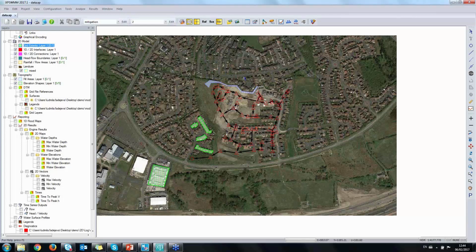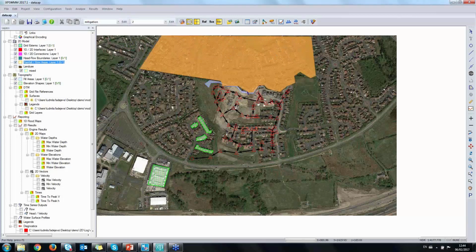potential land acquisition people. So if this is a developer and they want to buy land and they ask you what will happen, even without having the drainage system, you could just use rain on grid and see how the water would flow through the potential area. You could just quickly draw some houses with green items, where you think they will be, and you can see how things will change and what will happen.